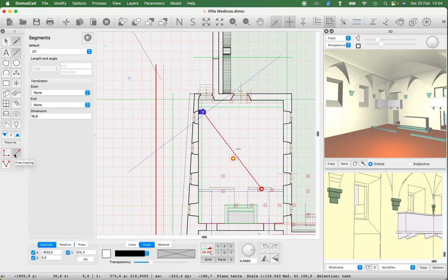To insert a line, press the mouse, drag it while holding down the mouse button, and release it at the end of the line. There are three ways to enter lines. The first way is free entry. Another input mode is horizontal or vertical. While tracing, the line assumes the direction closest to the horizontal or vertical from the starting point. In the third way, the segments are drawn with the angle set in the drafting machine.